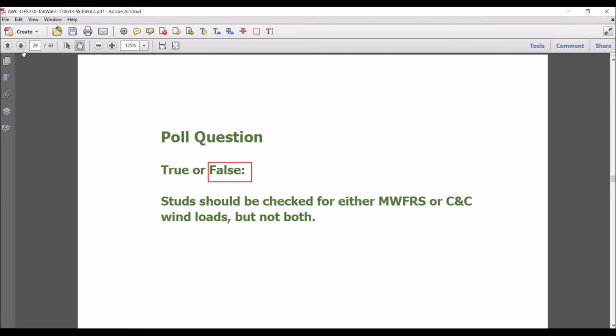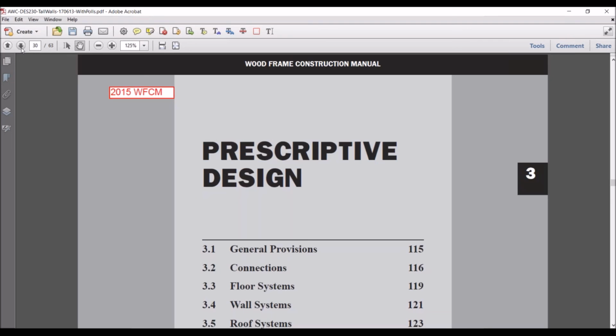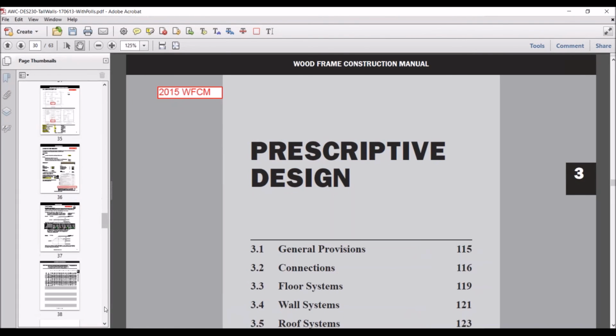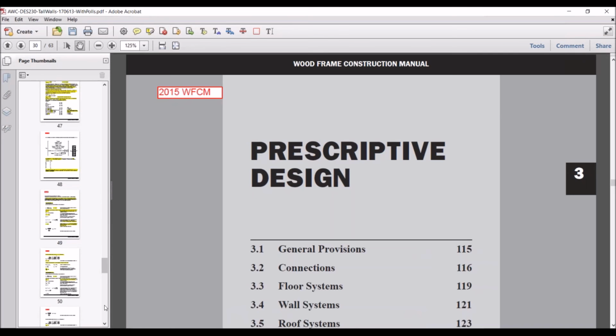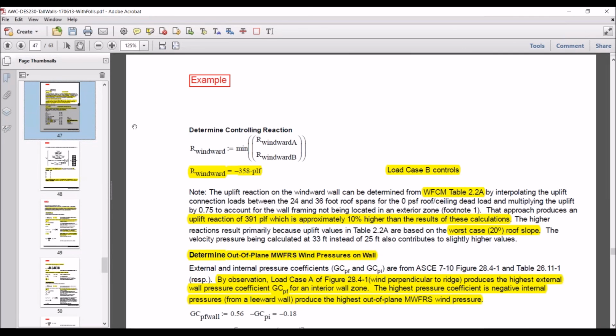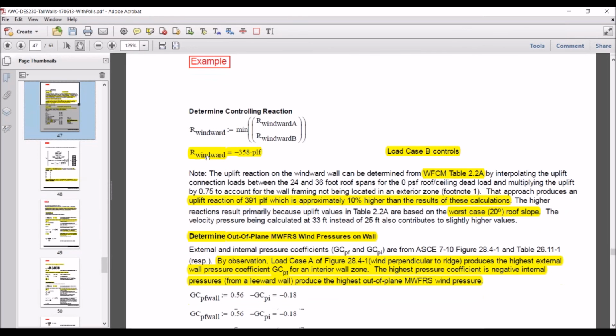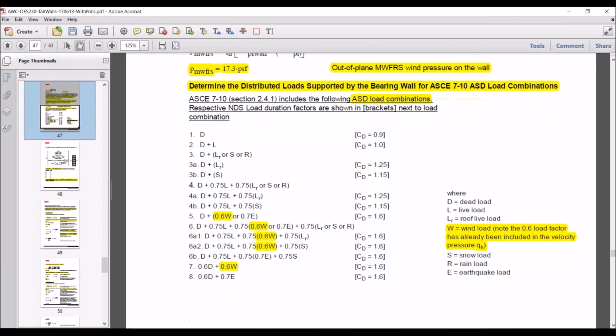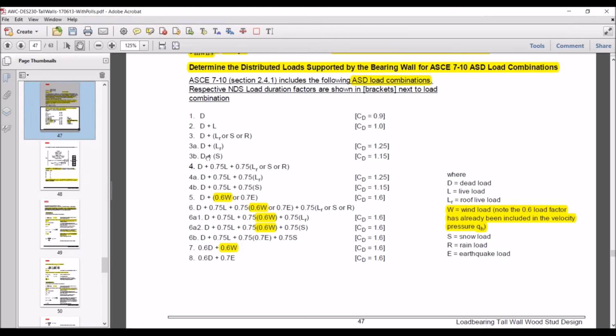Do you have a sense of when dead load might be the controlling load case? Yeah, it is not a common occurrence in wood that you get a dead load controlled design, but one example of where you might encounter that would be if you're designing a permanent wood foundation. You can get some soil loads on the members of the foundation that can be rather substantial and can wind up controlling over the occupancy loads. So that's a great example where it's imperative to check all of the combinations.